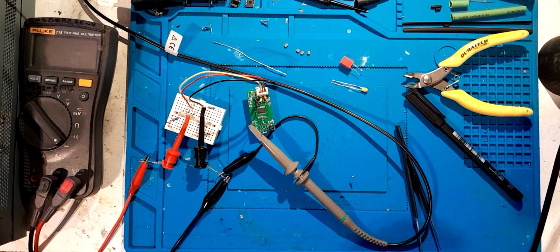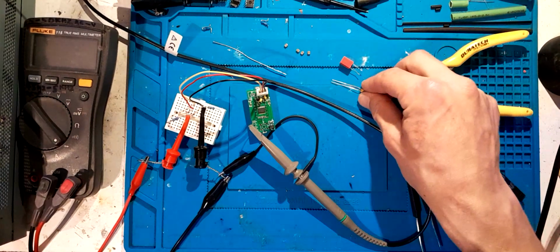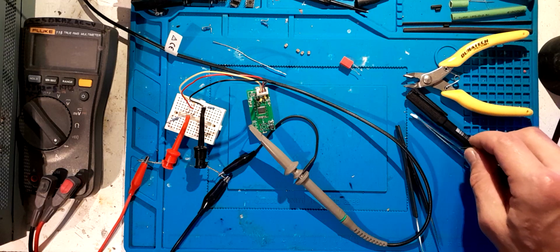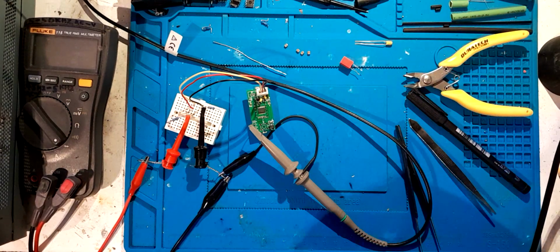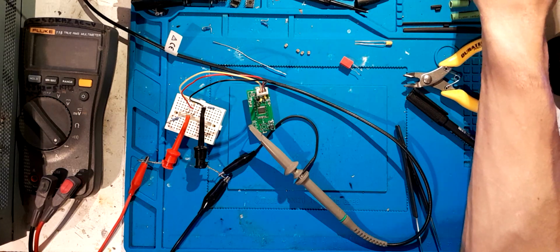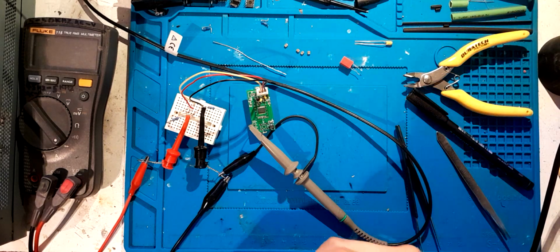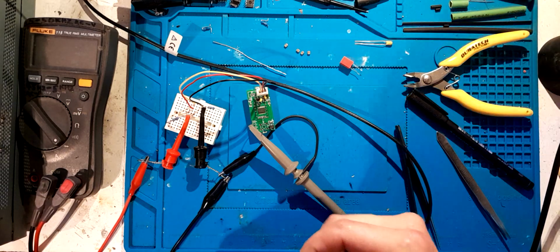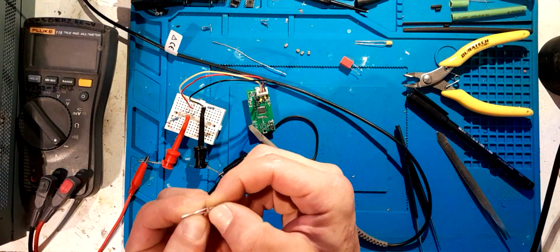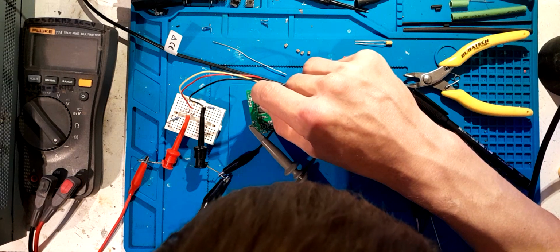VCAP, you know what, I'd like to look at VCAP quickly before I do that too. I think what I'll do, again, I'll grab this tan. Oh no, it's 10 mic. Let's grab 1 microfarad monolithic, and I'm just going to sit that across VCAP whilst observing the scope and see if it cleans the waveform up anymore.